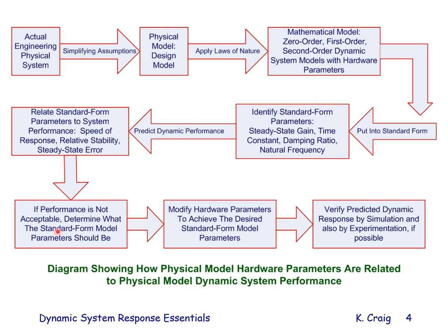So if performance is not acceptable, determine what the standard form model parameters should be to give you acceptable performance. Then modify the hardware parameters to achieve the desired standard form model parameters. Then verify predicted dynamic response by simulation and also by experimentation if possible.